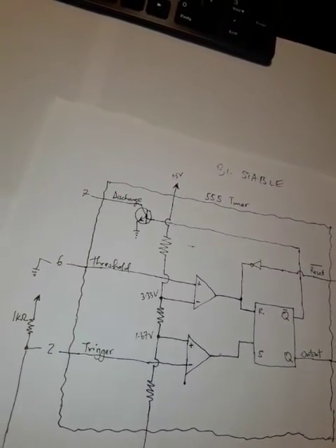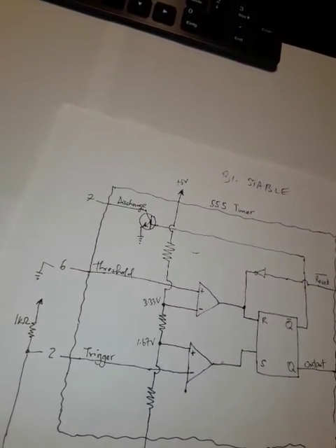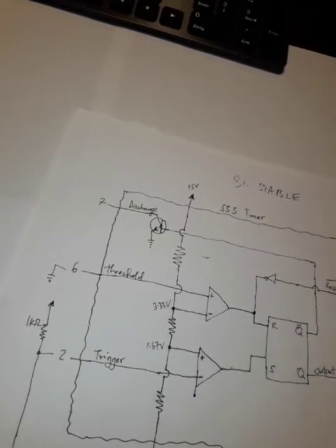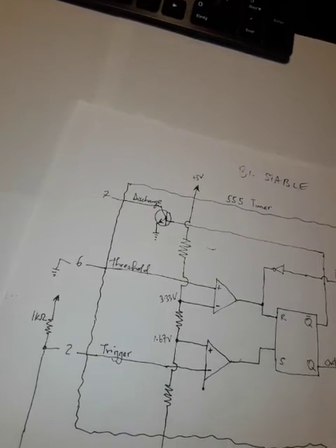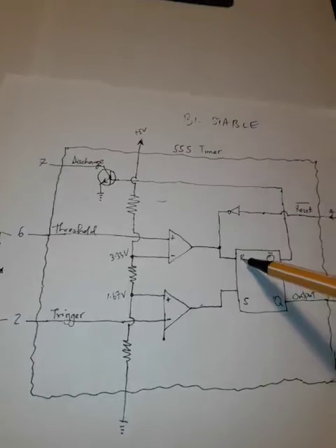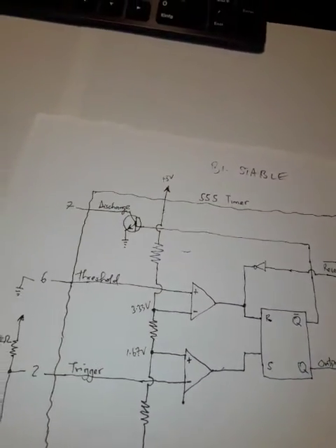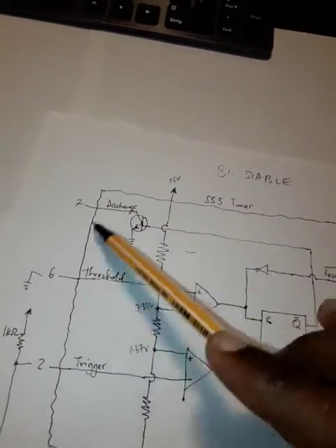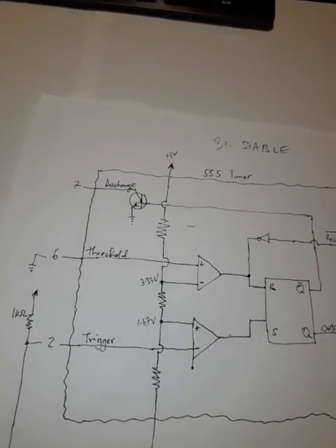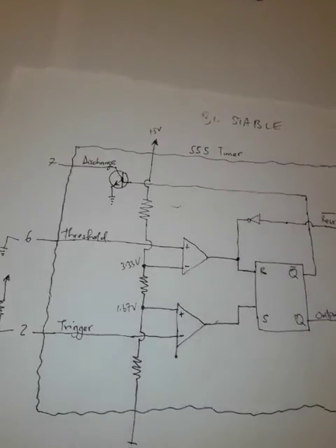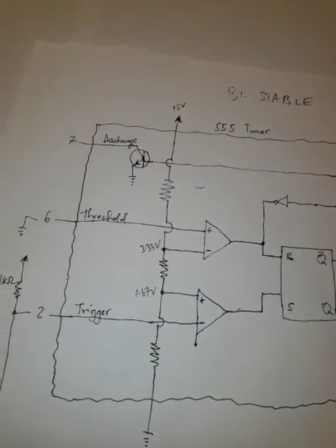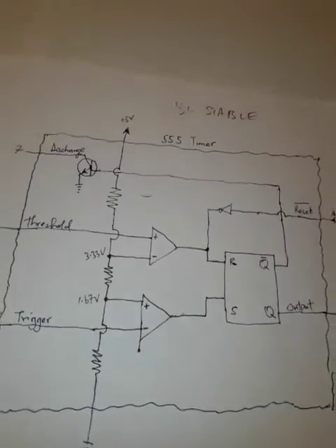and once I push it back to this point, so once the switch pole connects to this, it's going to set my reset part of the SR latch, and it's going to set it back to low. So I'm not really using any of these components on this side of the 555. So you might want to ask, why am I just using this as a switch? Why can't you just plug it directly with the switch with your voltage?